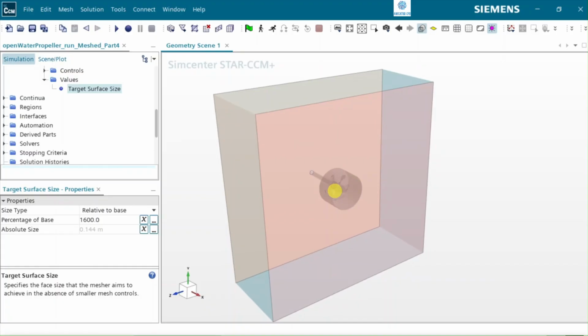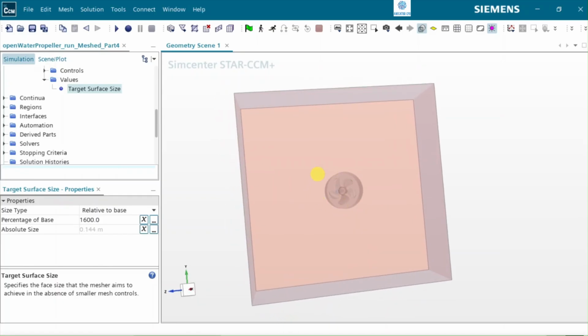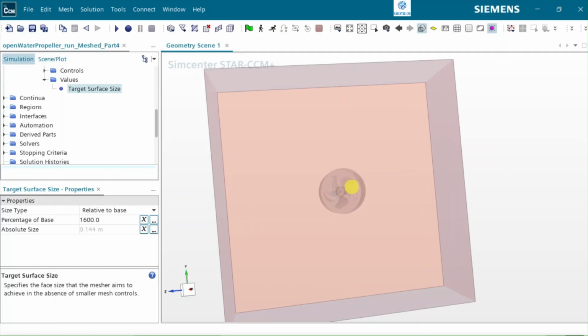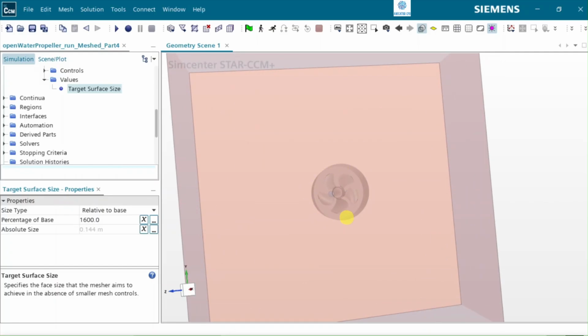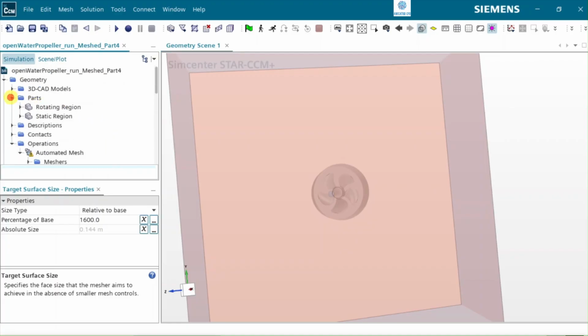Now remember in Chapter 1, when we meshed the rotating cube case, we refined the transition between rotating and stationary regions. That refinement must keep the aspect ratio and transition quality acceptable. In that example, we created a slightly larger cylinder around the rotating region and used it as a refinement region. We will do the same thing here.